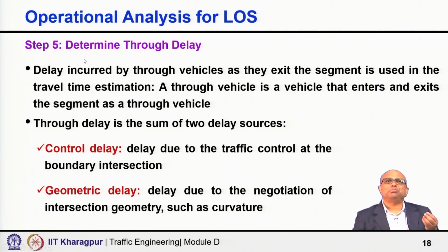Similarly, the next step is determination of the through delay, that is, how much delay through vehicles are incurring. The delay incurred by a through vehicle on the exit segment is used for travel time calculation, that is, how much time the vehicles are taking to travel the segment. So, the through vehicle delay is therefore very important. Now, what is a through vehicle?